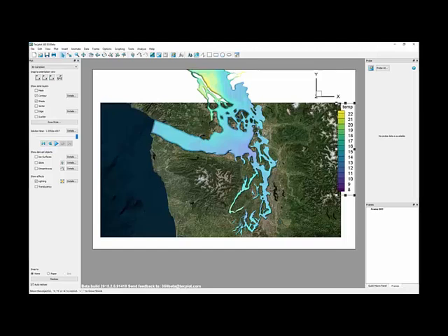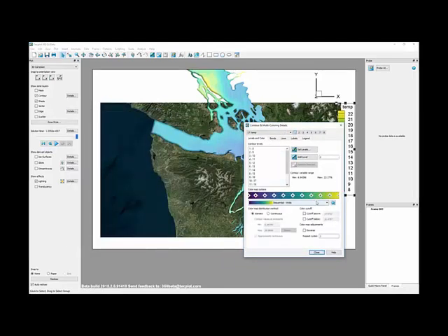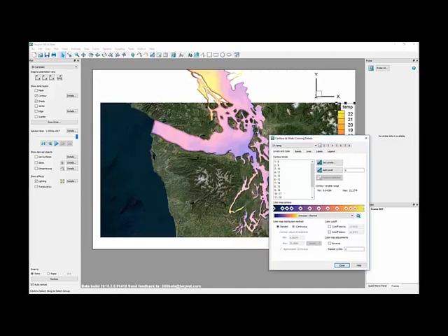Now we'll double click on the legend, and a better color map for temperature is actually one developed by Kristen Thyng. She's developed the CM Ocean color maps, and she's been nice enough to release those in open source. So we've been able to bring those into Tecplot. So let's choose the CM Ocean thermal color map, which is a nice one for temperature. And we'll do a continuous contouring, so you can see the difference between continuous and banded. This can give a really nice blended view.